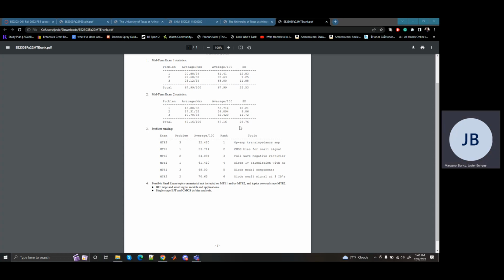So to turn it into a linear representation, you take the small signal, you take the derivative, and now this exponential term, at this point, the slope is linear, right? So at this operating point, we can approximate it to be a linear device. You do small signal analysis. Now you can do Thevenin's and all that stuff that needs linear devices.